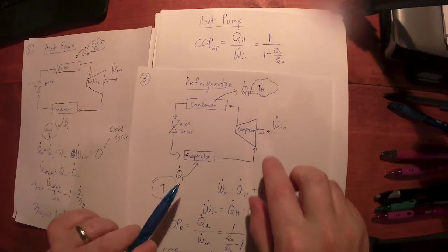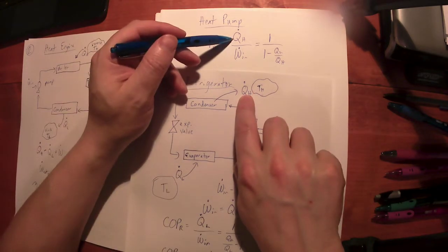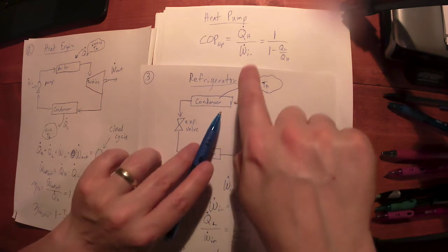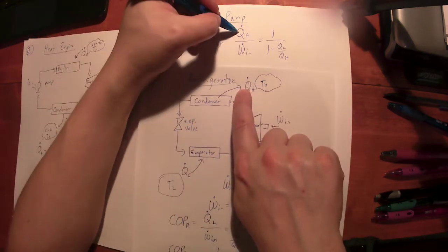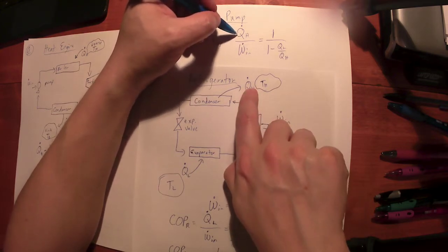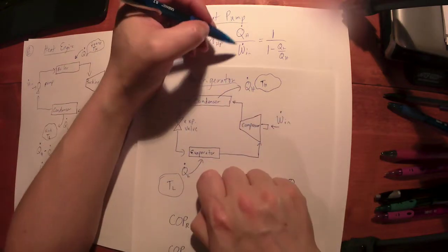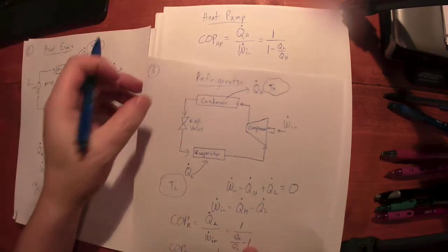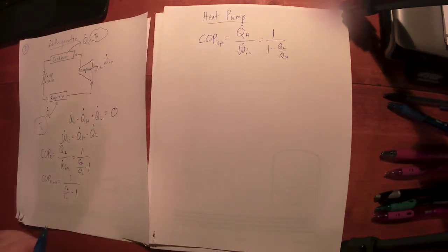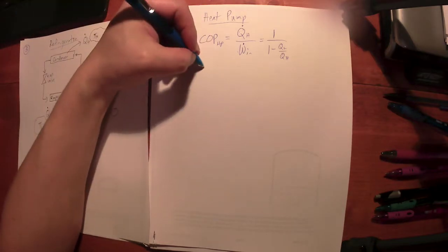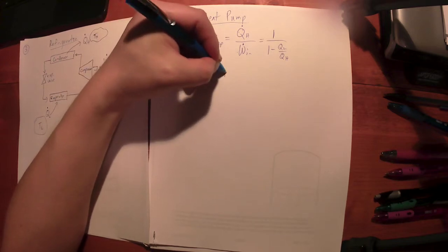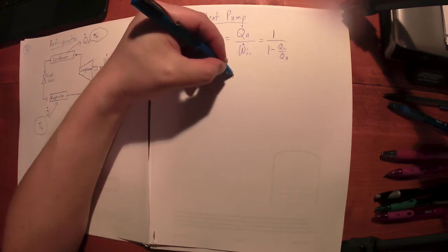Now, one thing to mention here, if I'm talking about a heat pump, because again, it's the same device, notice in a heat pump that what I want is always going to be the sum of these two. This in, plus this in, equals this out. This is always greater than this, because it's always these two added together. Coefficient of performance for a heat pump is always greater than 1. Coefficient of performance for a refrigerator is typically greater than 1, but for a heat pump it's always greater than 1. It always puts more heat into the high temperature space than the electricity we use to run it. That's the beauty of this device.